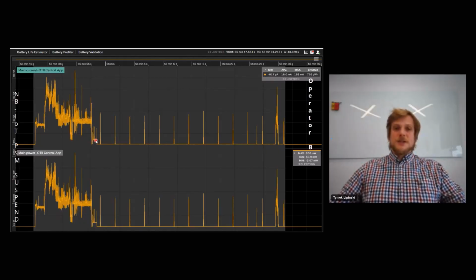Here I must have sent an AT command and woken up the modem interface. And then we go paging, paging, anything for me, hello, what's going on? Okay, nothing for me, let's prepare for suspend and go to sleep. And this cycle took 43 seconds and used 76 microwatt hours.